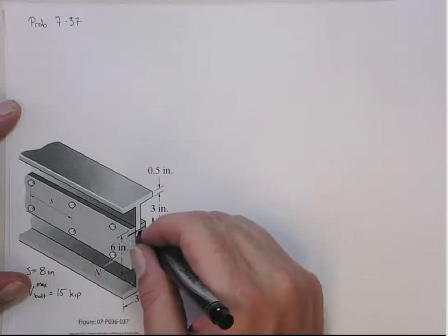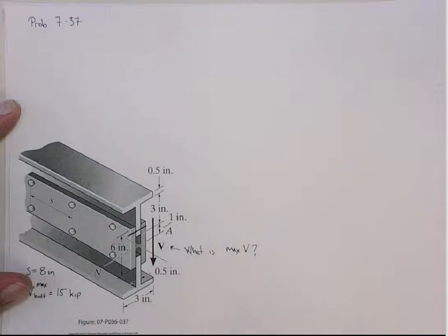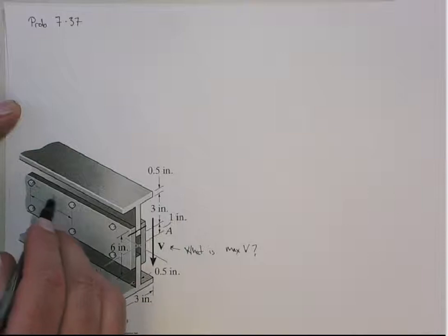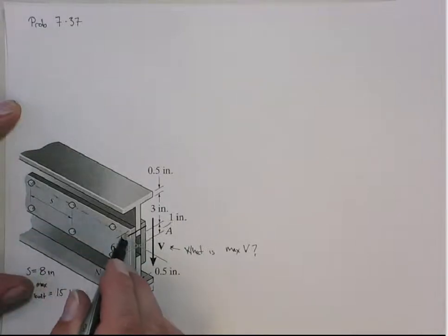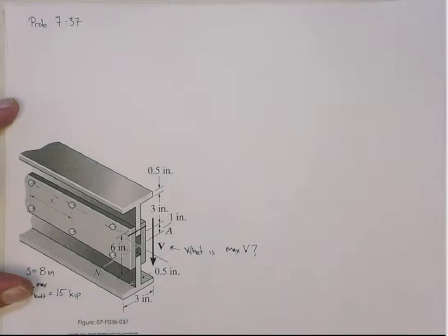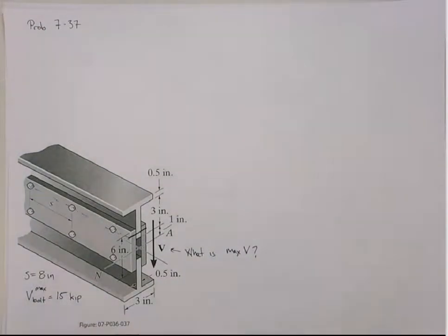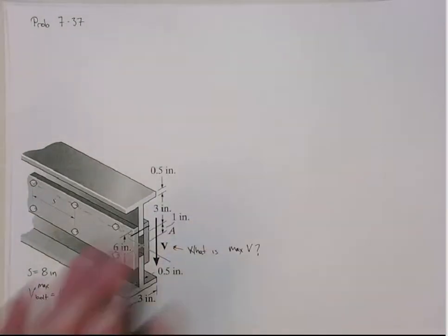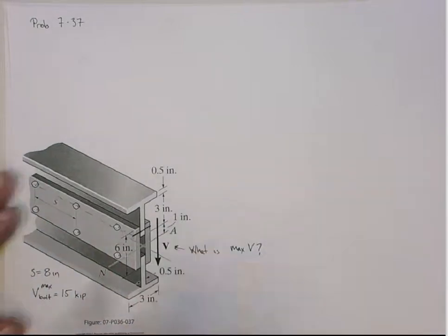Okay, this line here is the line where the bolts are going through, right? So I'm going to draw the center line through here. So that's the plane, right? If you look at this top section, these are always a little trickier to visualize. It always seems a little less believable that we actually use the transverse shear flow from VQ over I to get the force in the bolts when the bolts are on a plane that's perpendicular to this actual shearing plane, okay?